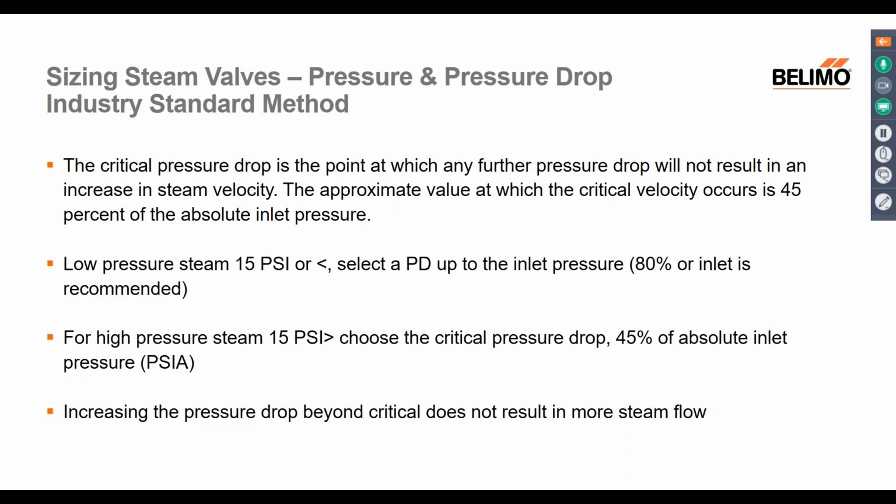And I'll show you how easy this has become over the years because of these new tools, Excel, and other tools that we have. But it's important, increasing the pressure drop beyond critical does not result in any more steam flow. But one of the biggest requests that I'll get is, oh no, I'm not taking 80% drop, I only want to take 50% drop. You can make the valve bigger.